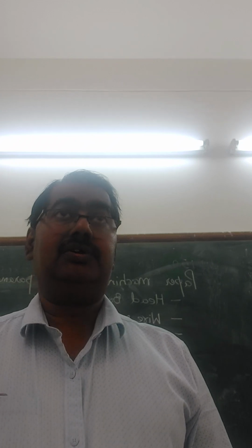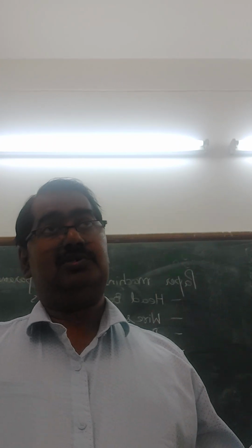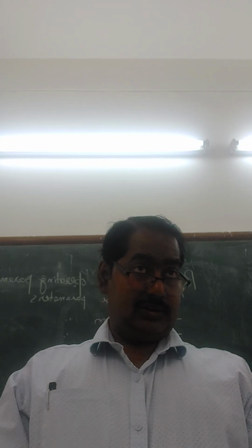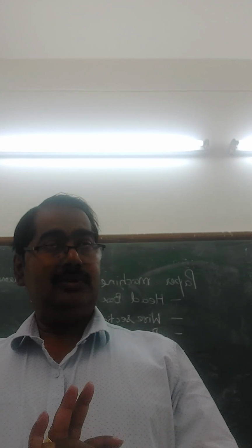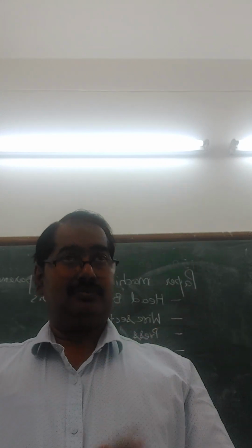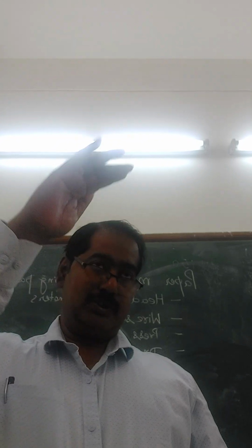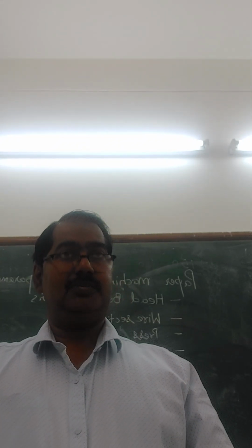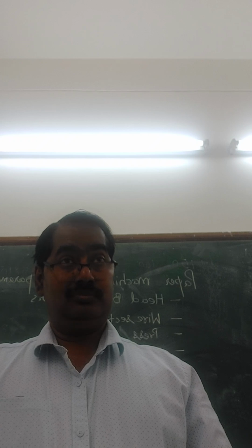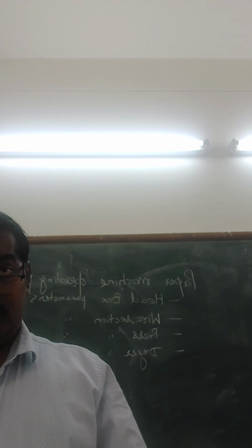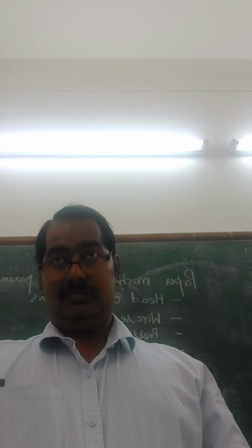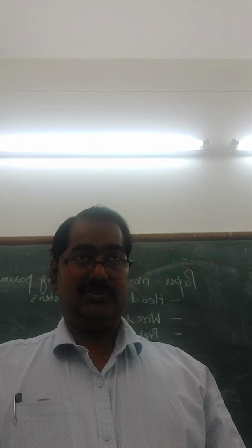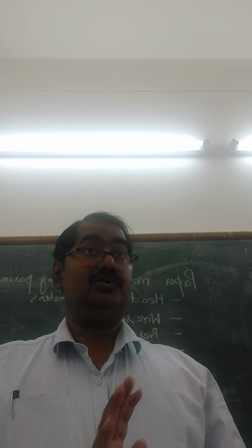But again, the pressure at which the slurry is coming out is very important, right? You can control the pressure by adjusting the level, and the second way is the extra pressure provided on top of the liquid level with the help of pressurized air. Is it clear? You can control the pressurized air pressure and the level inside the tank. The higher the pressure, the higher the jet velocity.